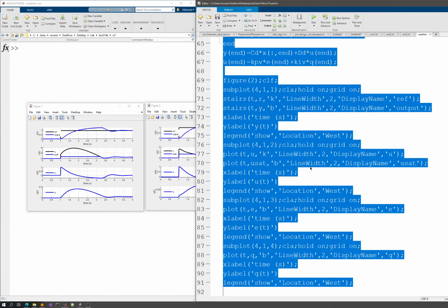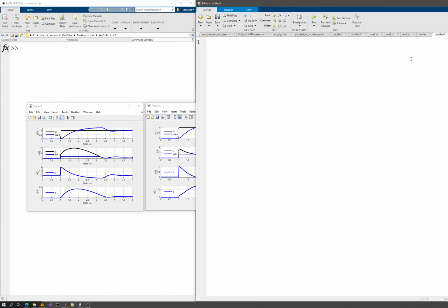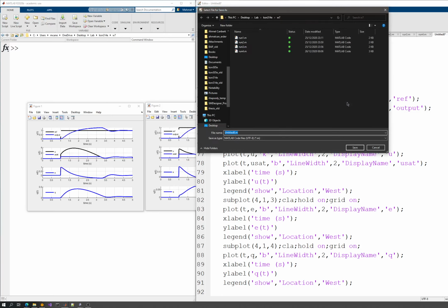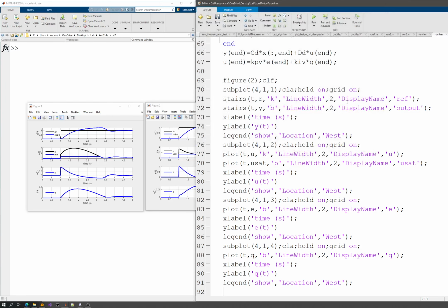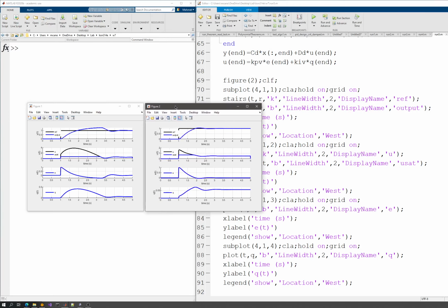Now I will copy and paste it again, but this time I will show you the other version of these structures. These strategies are called anti-wind-up, because it prevents the wind-up, and it does so by adjusting the integrator value or switching the integrator itself off. So it prevents this extra error or extra delay of the system just because of the integrator.